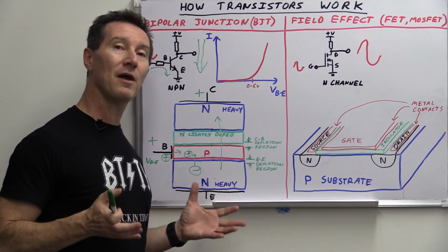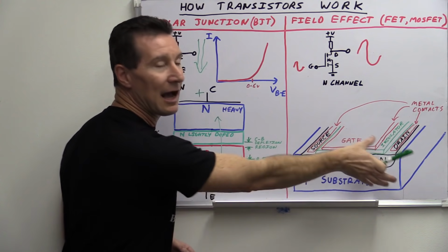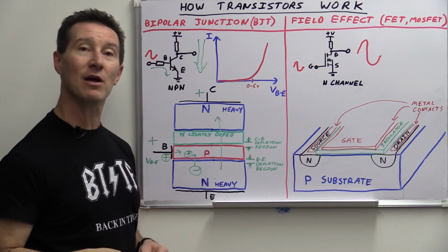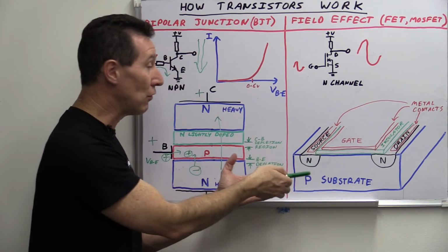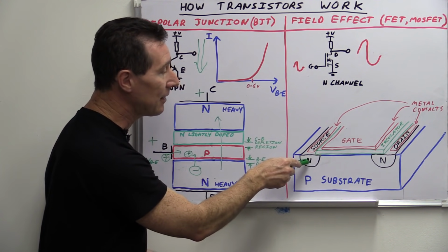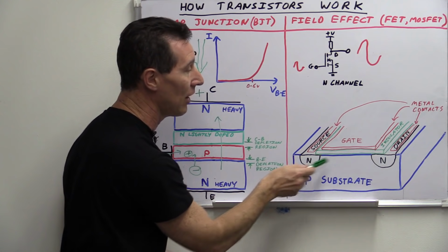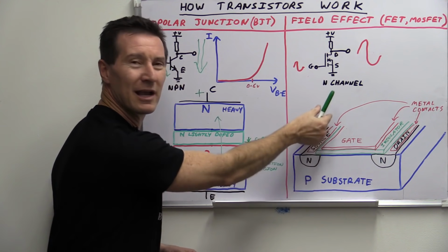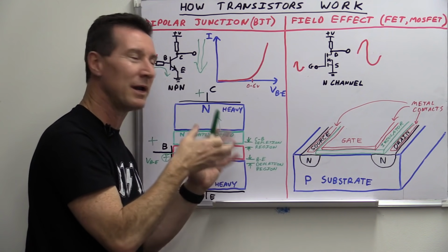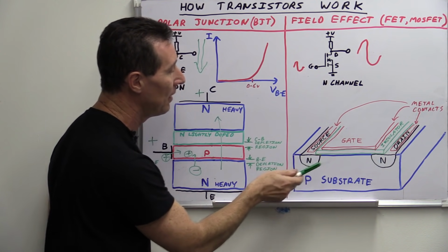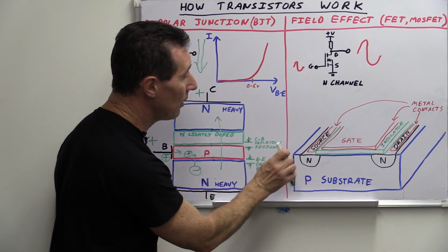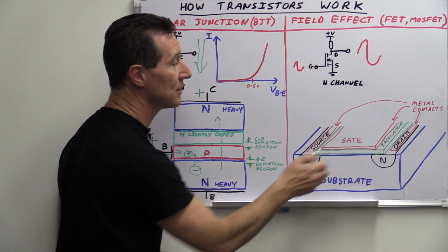So the way the MOSFET works in what's called a planar form here, this is how it's physically constructed on the silicon. We've got a p-type substrate base, it's of course p-type doped, and then we've got our two n-type doped regions. You can think of them as like a physical channel or whatever. It doesn't really matter how you physically think of them, but there's two n-type nodes here. So one is the source and one is the drain.